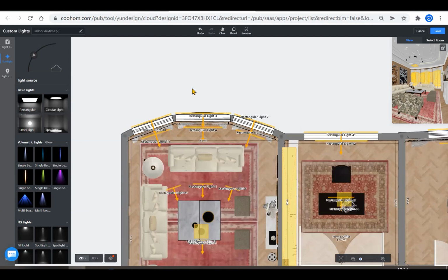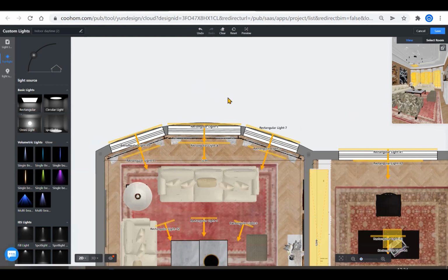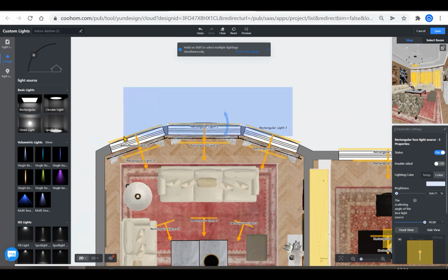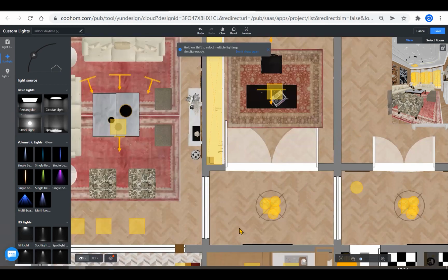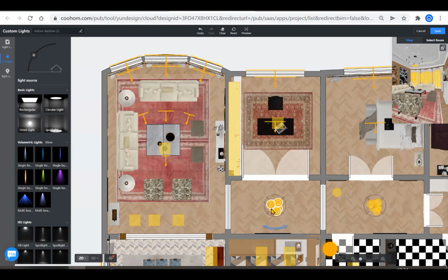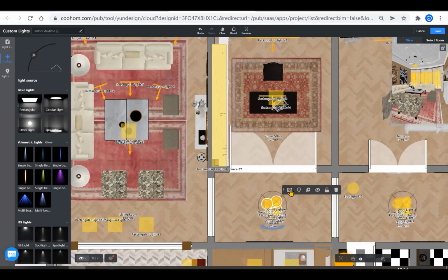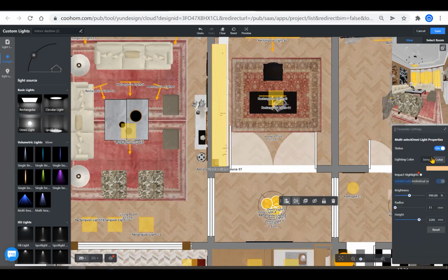And what if you want to adjust, let's say, more than one light? You could press Shift on your keyboard, not for surface light, but for the other lights, and then select several items, for example click Omni Light, so that you can change the parameters of them at one time.